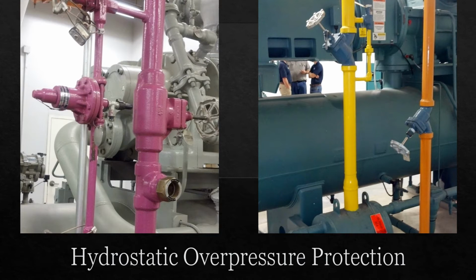1. Automatically during normal operation. 2. Automatically during shutdown, including an alarm or power failure. 3. During planned isolation for standby or seasonal conditions. 4. Due to an equipment fault. Or 5. Refrigerant pumps and connected piping must have a means of protection from hydrostatic overpressure. IIAR 9 clarifies that if hydrostatic expansion is only possible during maintenance or service operations, administrative controls are acceptable in lieu of a relief device.